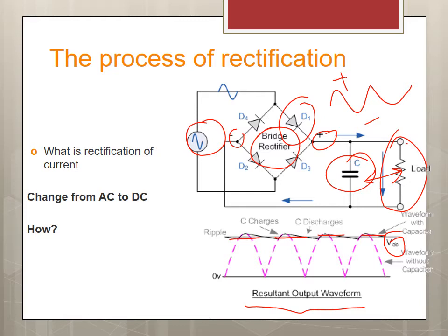So this is the simplest way to do a rectification system to change AC to DC, and probably you have that in your cell phone charger, because you're plugging that into the wall, which is AC, and you're getting DC. The same thing goes for car alternators, they produce AC and change that to DC. So all you have to know is this is changing AC to DC. We provide AC, and based on how much flame and how many ions we have, we will have some kind of indication of the intensity.